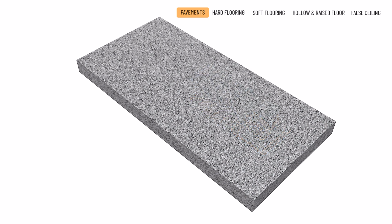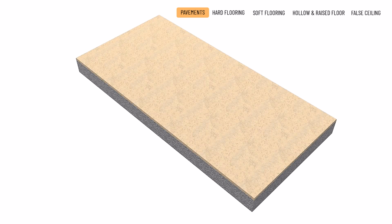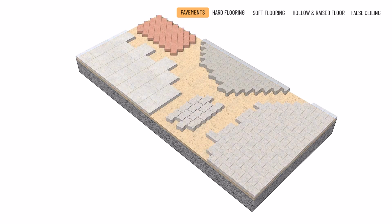On its surface, a 3 to 5 centimetre thick layer of sand is placed, into which the paver blocks are laid. The joints are filled with sand and, if necessary, slurried with water. Finally, the completed pavement can be compacted using a rubber mat compactor. For heavier loads, a concrete or reinforced concrete slab is required.